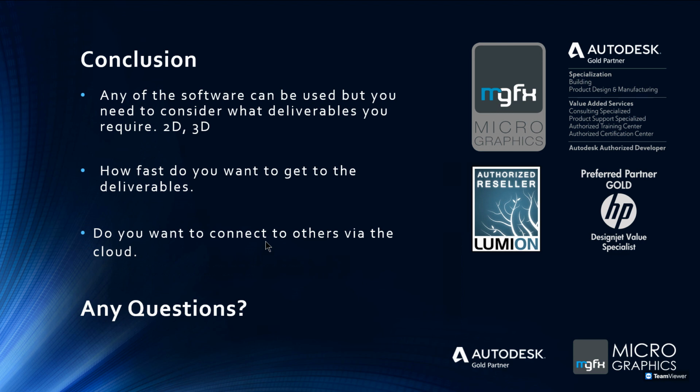The idea behind Forma is just to create the concept. Once you've created the concept, looking at sun angles and some design considerations with regards to the site, then you stop basically and pass that Forma model over to the Revit environment. The link between Forma and Revit is very good, so the information that you've designed within Forma just goes into Revit, where you create the documentation for that design.